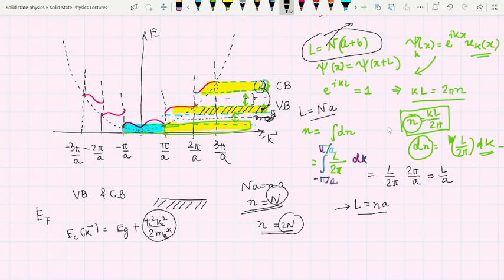What is effective mass? Inside the crystal, unlike the ordinary electron mass, the electron has a certain different mass, which is known as the effective mass, which results from its motion inside the crystal. By analogy with the free electron, where the energy is ħ²k² by 2m, we can represent the energy inside the crystal of the solid state device.